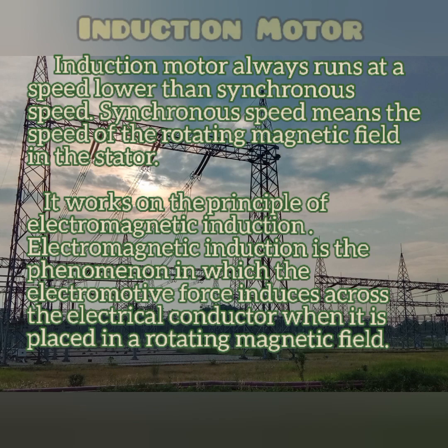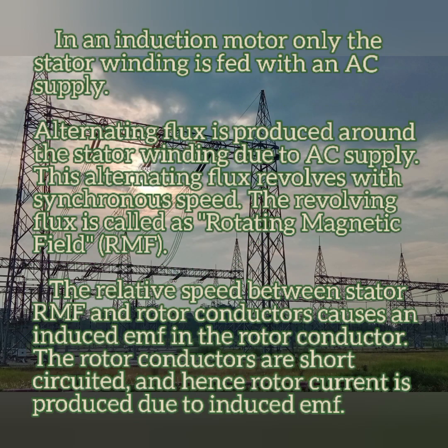It works on the principle of electromagnetic induction. Electromagnetic induction is the phenomenon in which an electromotive force is induced across an electrical conductor when it is placed in a rotating magnetic field. This rotating magnetic field is produced in the stator, in which the conductor is placed, and that conductor further moves according to the magnetic field. This is one of the main types of asynchronous motor, which means the induction motor is an asynchronous motor.